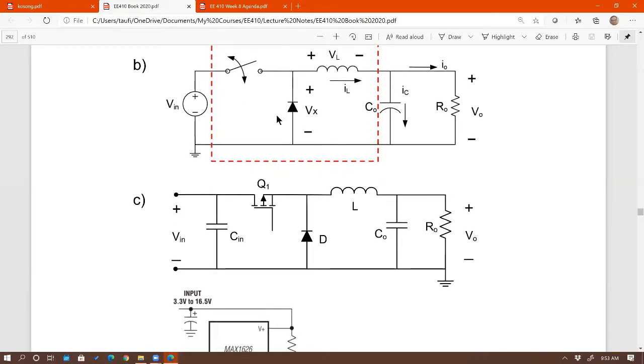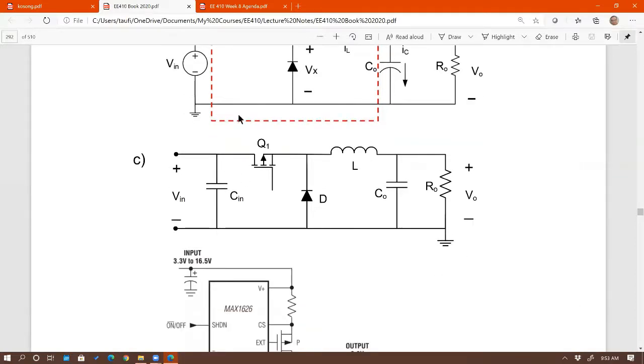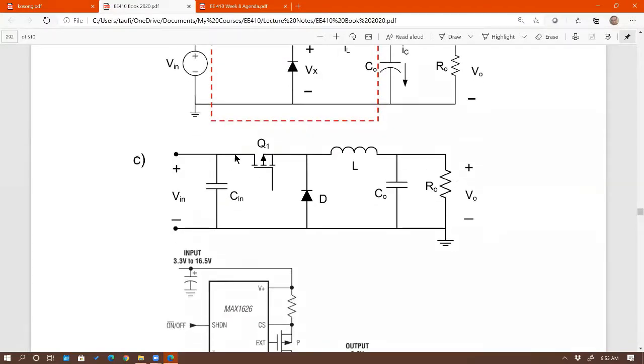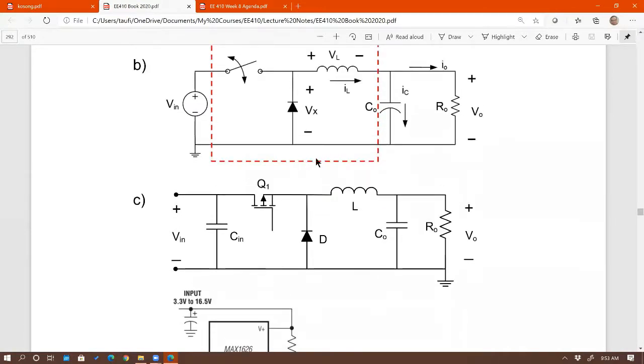Now, again, in many textbooks, that's what you'll see, right? And again, this is a learn by doing school, right? I'm going to go a step ahead of that one, a step more than this one. Out of this class, you have to understand that in real world DC to DC converters, you must have the first one, the controller, and the second one, the input capacitor right here, right? So this is one thing that's always missing from, like I said, many textbooks. They always show the output capacitor, but rarely show the input capacitor.